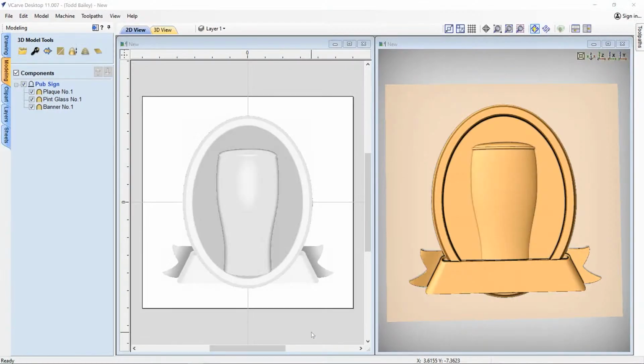Base heights aren't just for components. This is something that a lot of people either don't know or don't use very often and sometimes forget about, is that we can actually add base heights to levels. If you do that, anything that's on that level will end up having a starting base height right off the bat. What I have in front of you right here is a really good example of that.